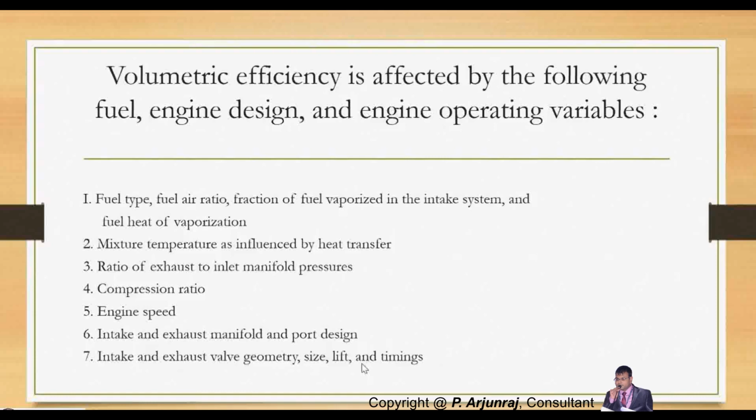It is also based on the fuel type. I told you there are two types of fuel, gasoline and diesel. The volumetric efficiency of diesel is going to be higher than that of gasoline, because in the case of diesel only air comes in, whereas an air fuel mixture comes in the case of gasoline. And when this volumetric efficiency is higher, it will also have an influence on the mechanical efficiency and the combustion efficiency of your engine.